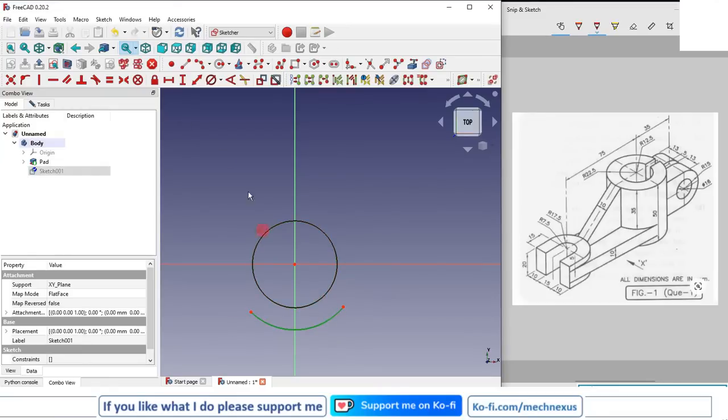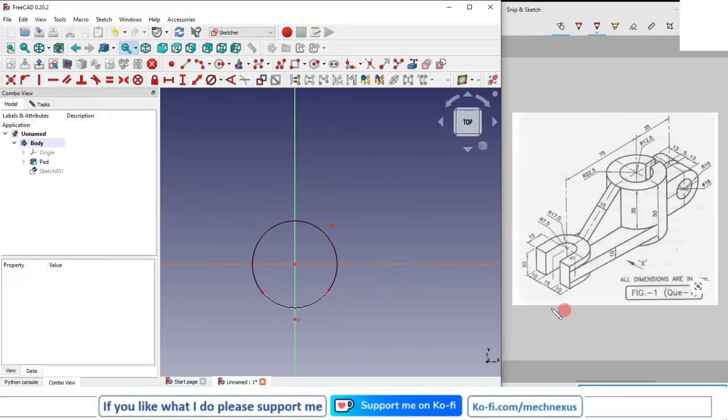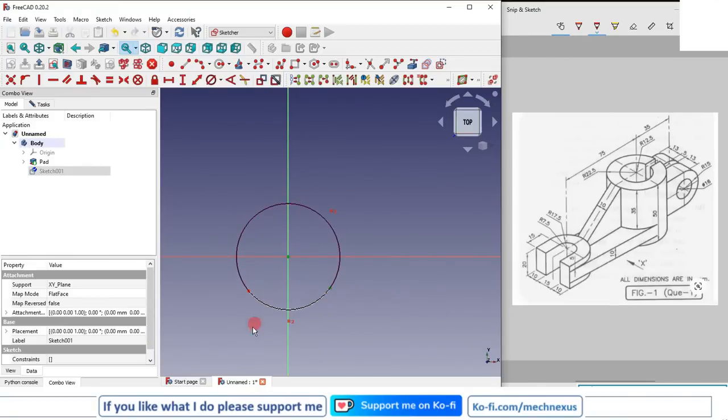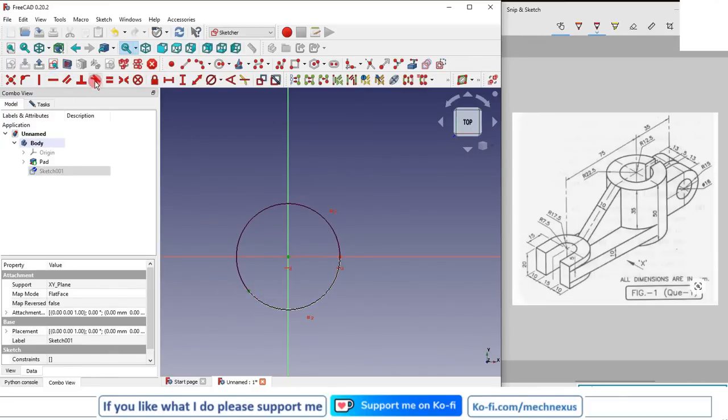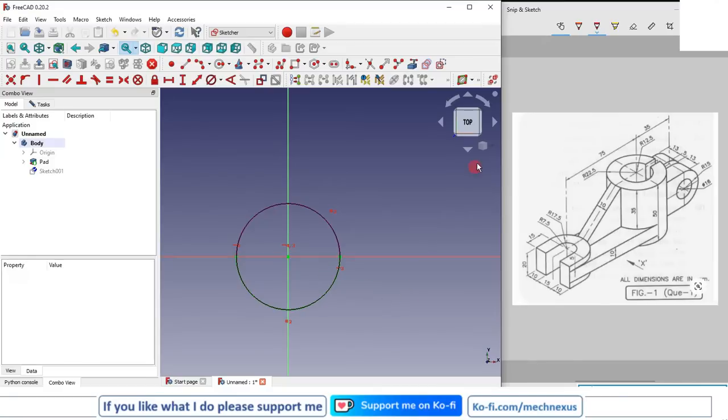I will select this and this, and I make it equal, and I will select this point and give the horizontal constraint. Similarly this one and this one, and I will give the horizontal constraint. Now the total width is 10 plus 15 plus 10. So 10, 10, 20 plus 15 is 35.